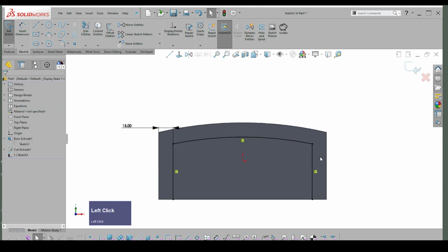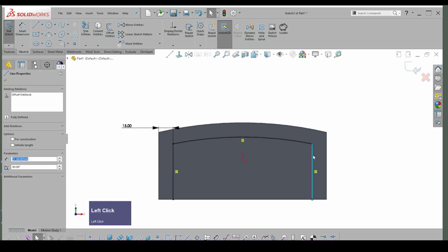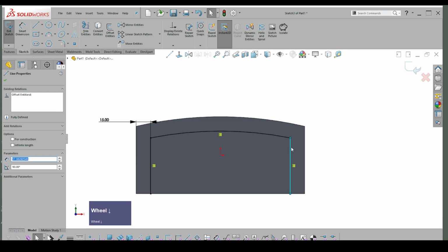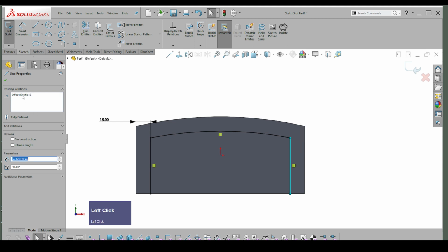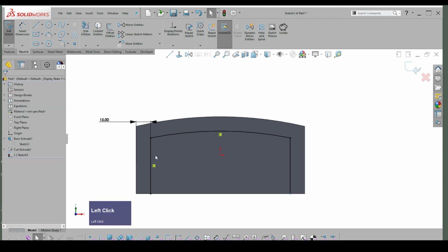The difficulty here is that if I want to change the side dimensions relative to the top dimension, or if I want to change the dimension of any one of these, I have to go and cut away or get rid of all of the offset entities associated with an item. You'll see, even though I've gotten rid of that offset entity, it still turns black.